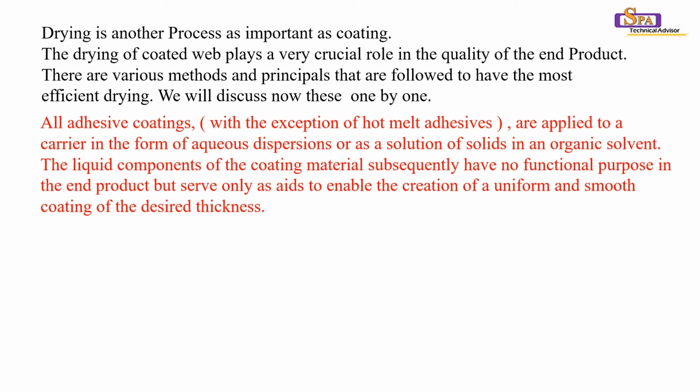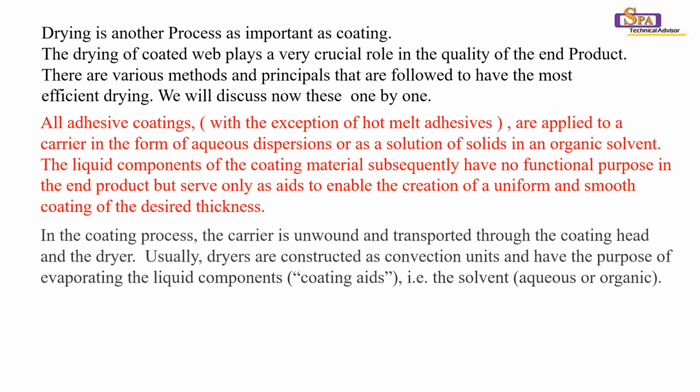All adhesive coatings, with the exception of hot melt adhesives, are applied to a carrier or to a web in the form of aqueous dispersion or as a solution of solids in an organic solvent. The liquid component of the coating material subsequently has no functional purpose in the end product but serves only as an aid to enable the creation of a uniform and smooth coating of the desired thickness.